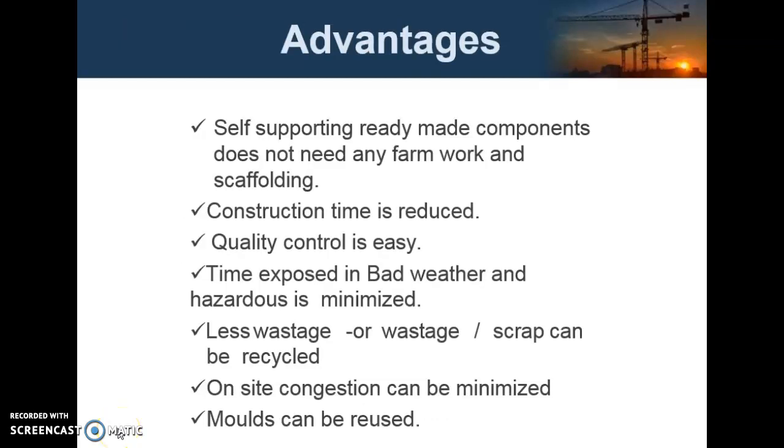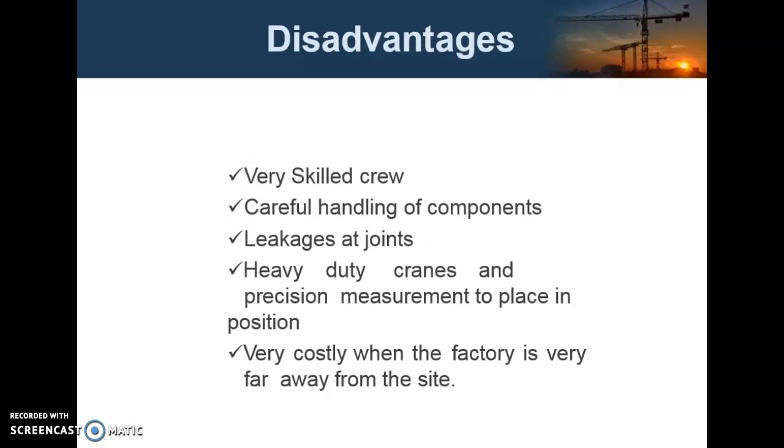The advantages are self-supporting ready-made components can be used, construction time much more reduced, quality control maintained, time exposed in bad weather conditions is reduced, less wastage, and on-site congestion can be reduced.